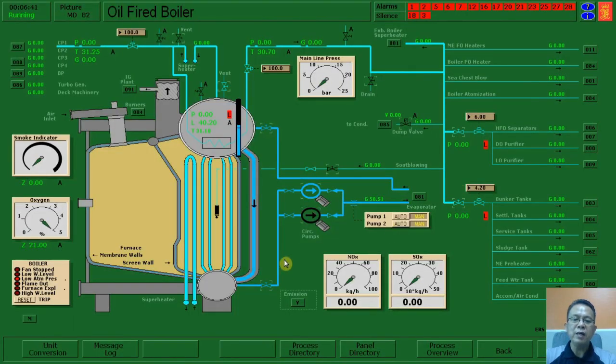And in here, starting the circulating pump, going to the economizer and then to the steam drum, we can find the controller here for auto. So let us put pump 1 as well as pump 2 in auto mode. Why is it needed to put pump number 2 in auto mode? The answer is, if there is an abnormality and circulating pump number 1 stops, then there should be a backup, so circulating pump number 2 should start immediately. So it needs to be put in auto position.